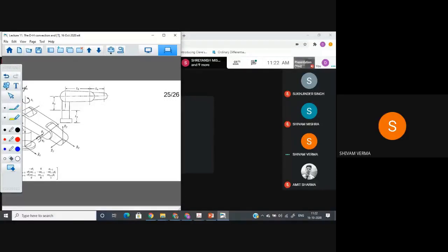Other joints, like a spherical joint, can be realized using a combination of more than one revolute joint. So you should know this fundamental transformation, and then you can extend it to the other joints.